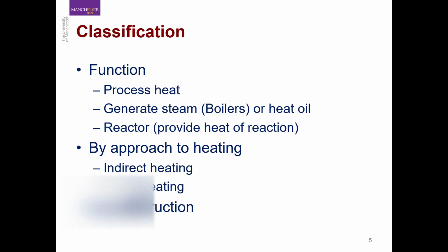You can also use fired heaters as a reactor, for example. So instead of using steam or hot oil to heat your reactor, you can actually put the reactant system inside a fired heater if you require very high heat, and then you can provide heat to the reaction, and that is mostly the case for endothermic reactions.